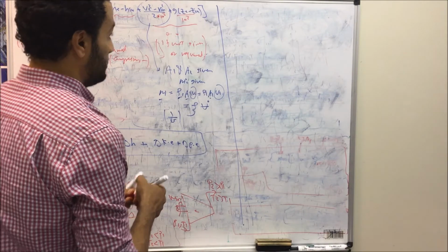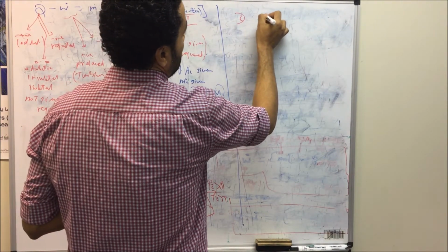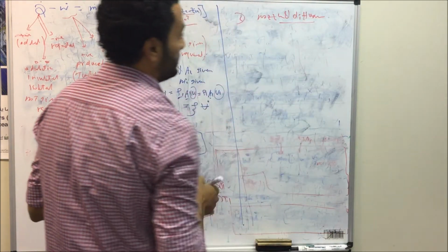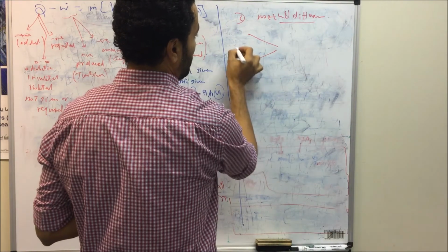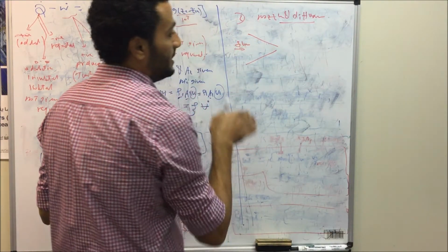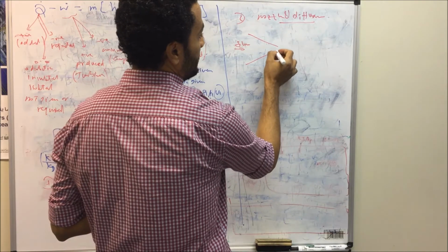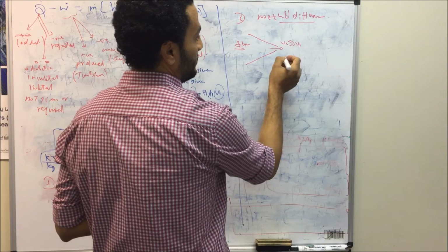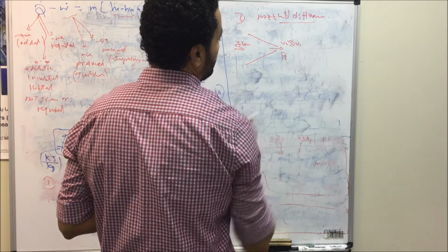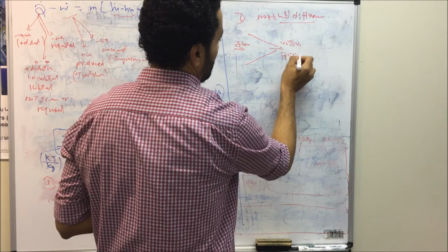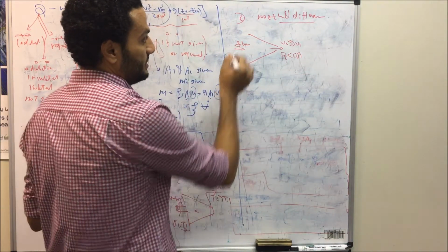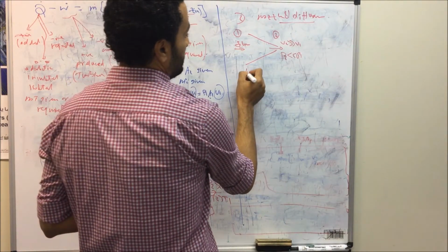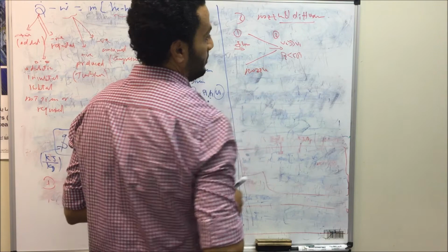But let's consider another special case, which is the case of nozzle and diffuser. In case of nozzle, we have flow coming to this nozzle. The area is contracted in the flow direction, so the velocity V2 at the exit is increased. V2 is much greater than V1, and based on that P2 is reduced, should be much less than P1 at the inlet section. Let's say this is the inlet section 1 and this is the exit section 2. This is the case when we have a nozzle.